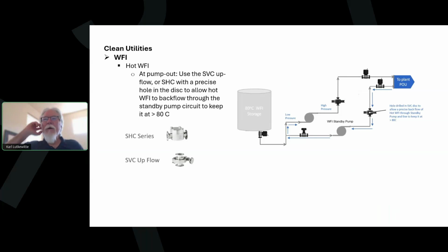Here's another really interesting one on hot WFI. Several years ago, a customer approached us after learning about our check valve, and he said, can I drill a hole in the check valve disc so that I can allow a backflow of my hot WFI standby pump loop, so that I can keep this standby pump at least 80 degrees C, so that it truly is standby and ready to go at a moment's notice?